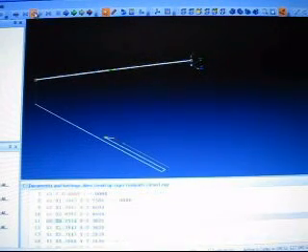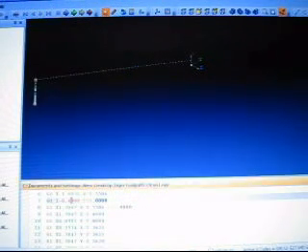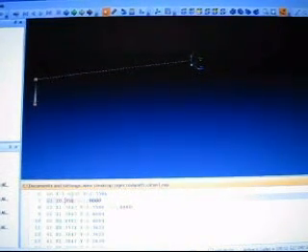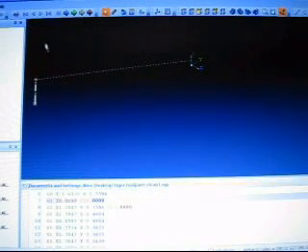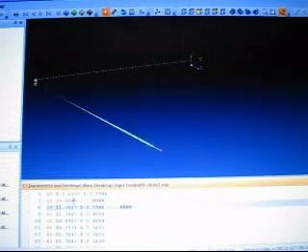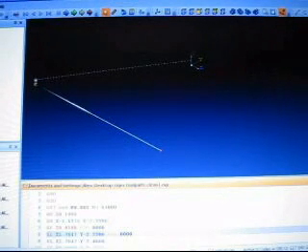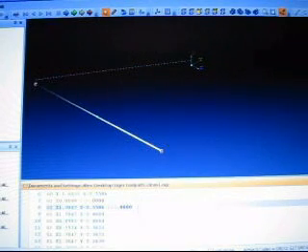Okay, so what I'm going to do is back up to this line right here and modify it. Instead of coming down to minus 0.4, I'm going to come down to 0.01. Okay, so just off the part, and now my next line is going to take me over. And if you touch that line behind it, it updated on the video for you. So now all I want to do is go back to this line of code which we already copied. I'm just going to enter in a space